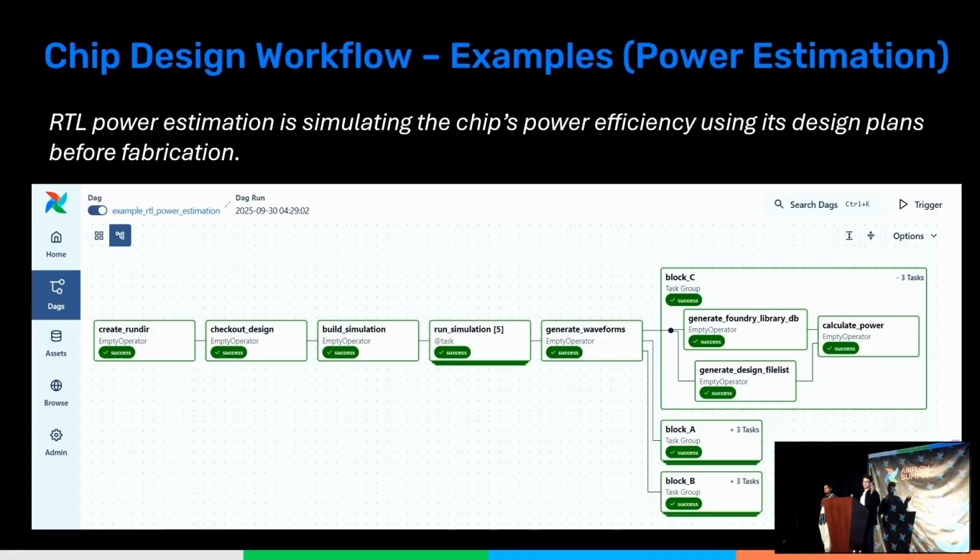If you look at the power team, you might do something a little different. You run the simulation, but on top of that, you generate waveforms, which you can think of as a time series graphical value of every single signal in your design. We have big chips with a lot of different layers to them, so this is a ton of information that may get dumped into a waveform output.